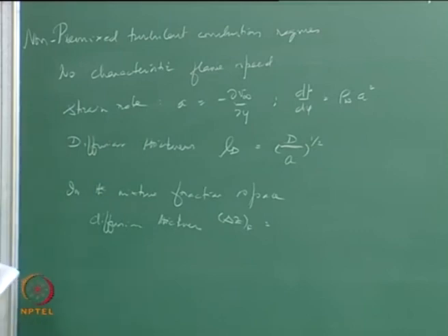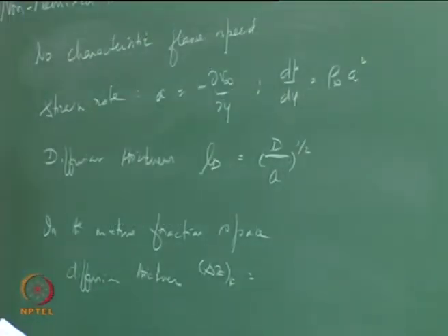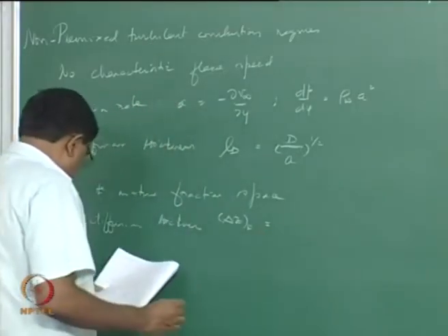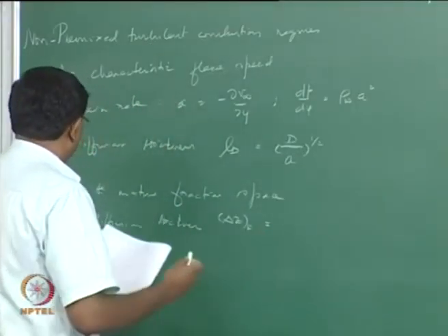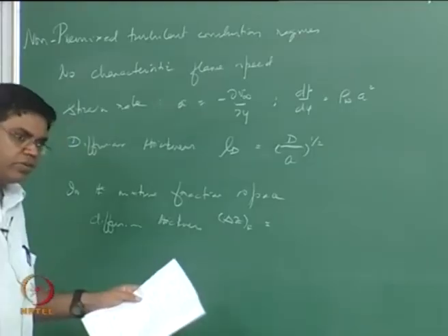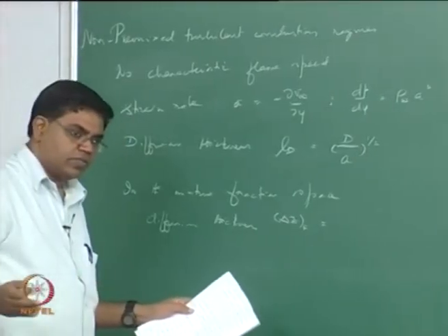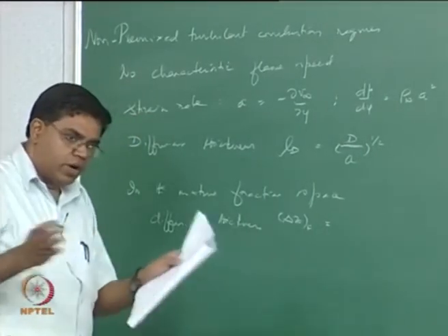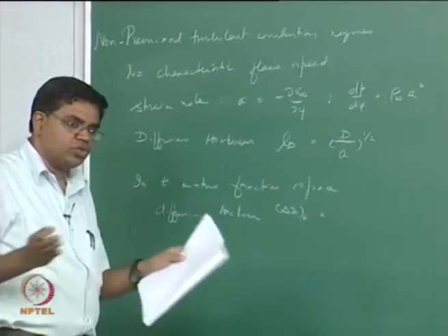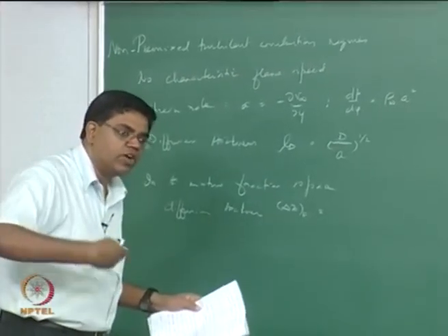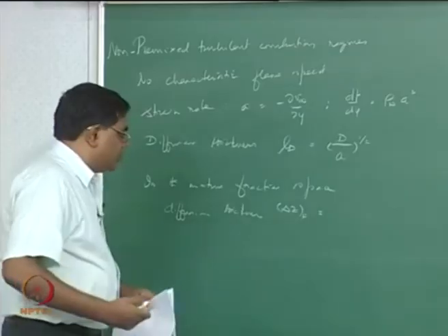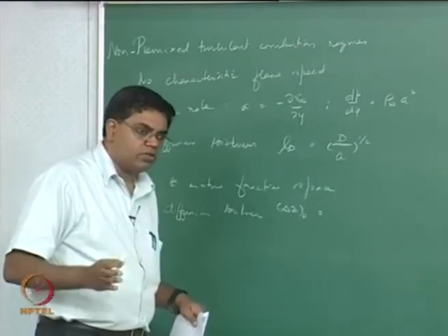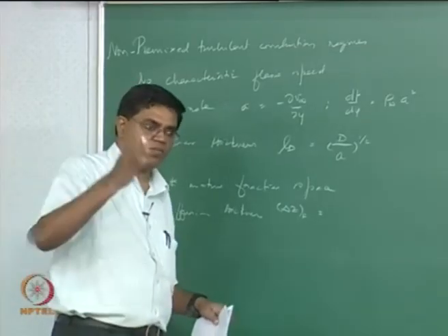Again the subscript F is corresponding to flame here, because we are looking at the diffusion thickness around the stoichiometric surface, right, because you have the flame and then you now have a certain length scale associated with the flame that the eddy wants to interact with. So in the mixture fraction space it's always about the stoichiometric mixture fraction where the flame is.